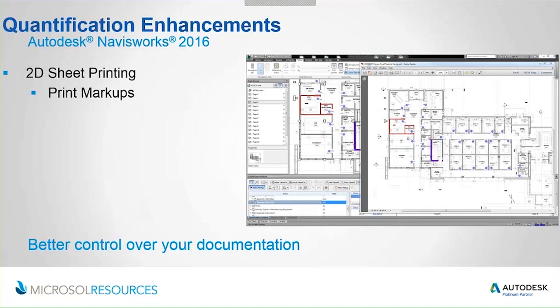But basically, having the ability to take those markups that you're doing, you're changing colors of walls, you're doing areas, you're counting how many walls of this type I have, you're making those blue, you're making them red. You're going to be able to take those individual 2D sheets and print them right in Navisworks. From your analysis or from your review, you can also take the takeoff and the item catalog and report that as well.